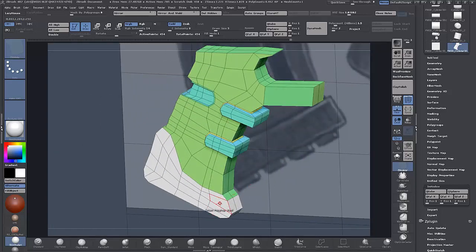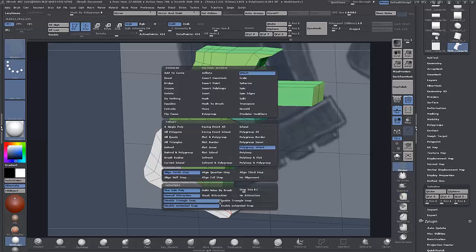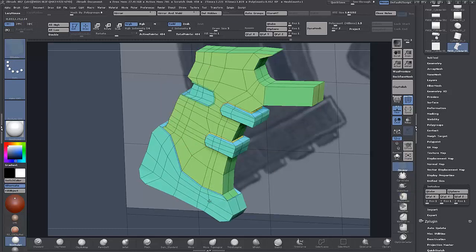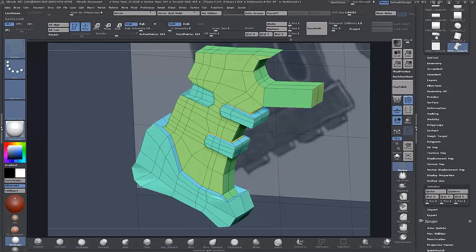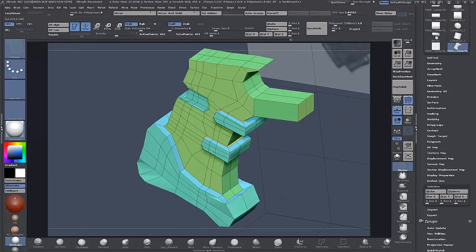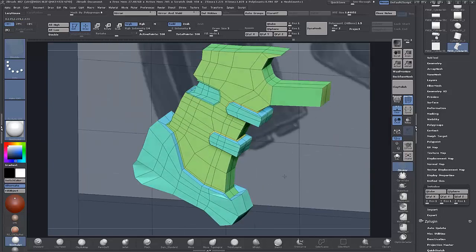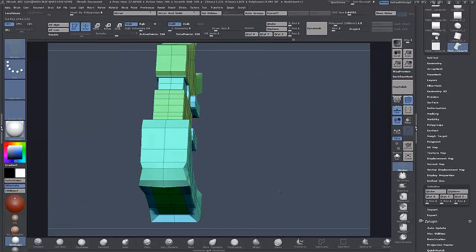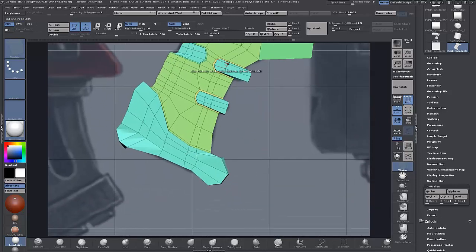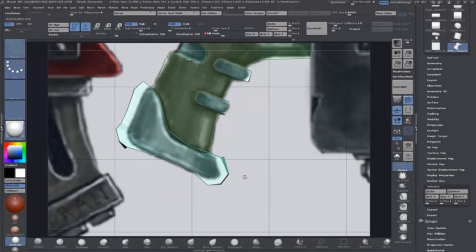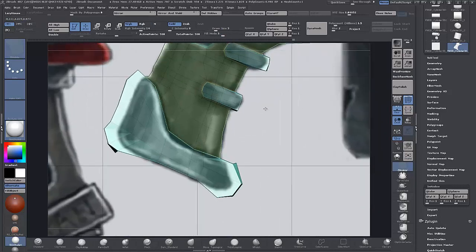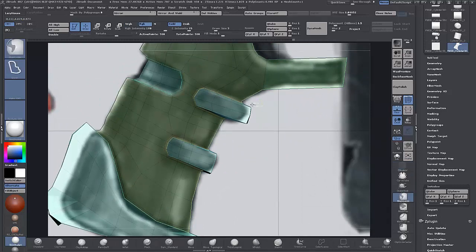And we'll Q mesh these. Q mesh a single poly. Just have a look now and see what that's like. We can, as I say, add in edge loops just to tighten up, which is what we're going to do now. Just add one in there. And now we might want to just shape this stuff up that we've added. You see it's come out way too far, so it's the same as what I did here. A bit of reshaping to do here as well.